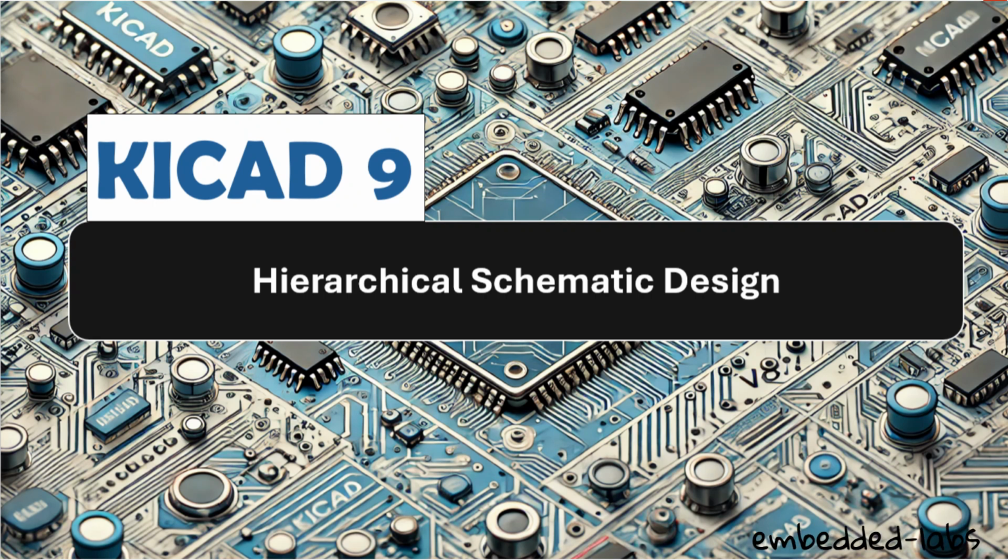Hello everyone, in this video I'm going to show you how you can use KiCad to create a hierarchical schematic. Now, there are many advantages of doing a hierarchical schematic design. One of the advantages is that it is easy for you to read the schematic. The second advantage is that debugging becomes easier, and the third, you can easily reuse the components.